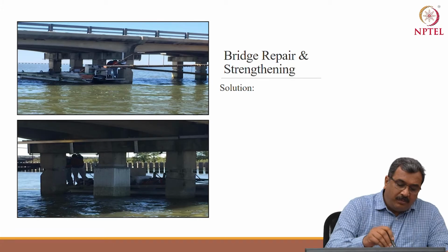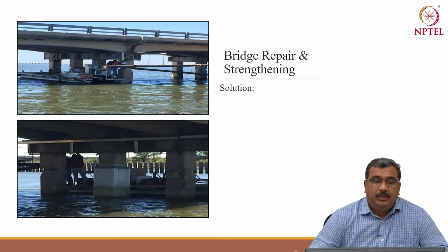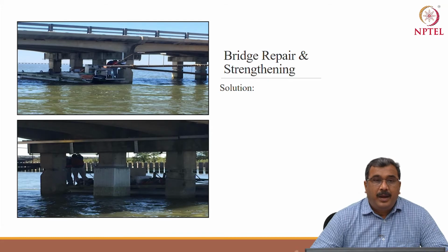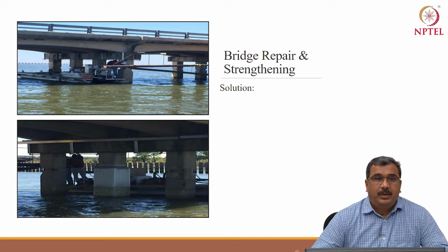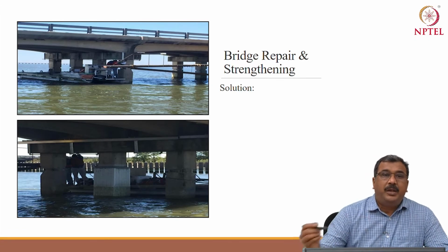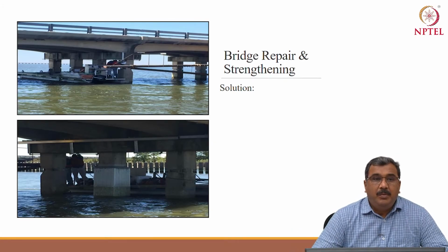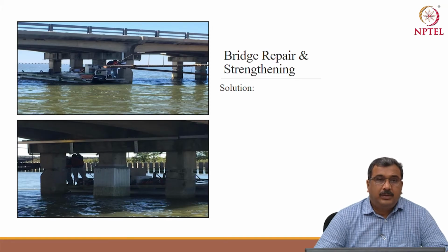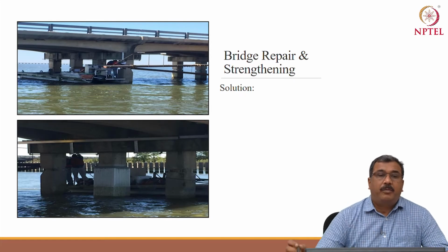You can see the column broken for establishing the connection between the zinc and the rebar, and the length of the anodes was such that because of the cloth, by capillary or wick action, this brackish water will keep the zinc activated, will keep the zinc corroding, so that the steel is protected from corrosion.